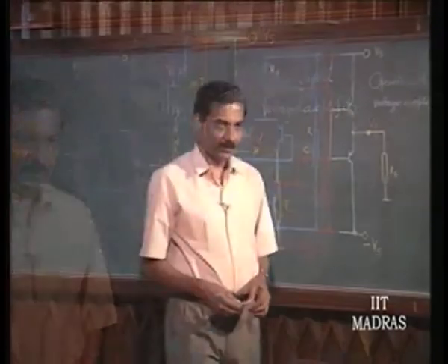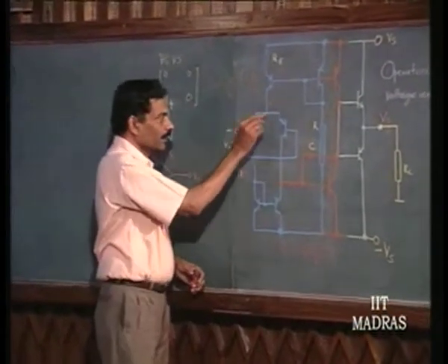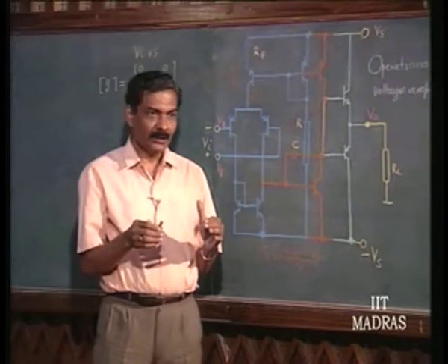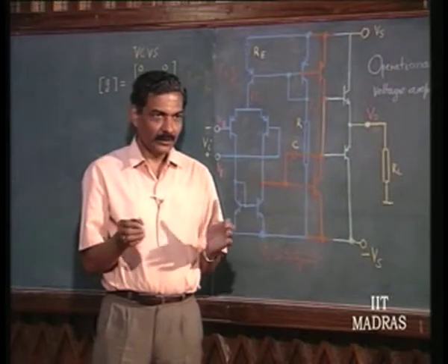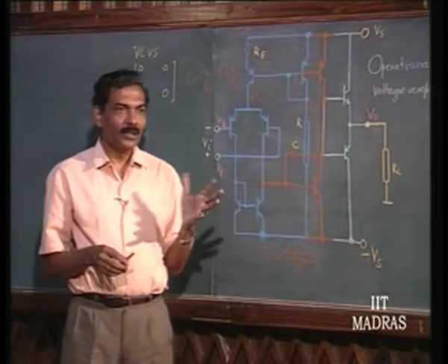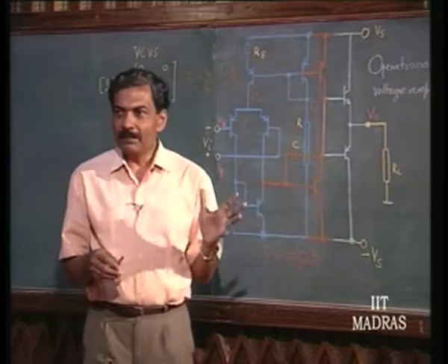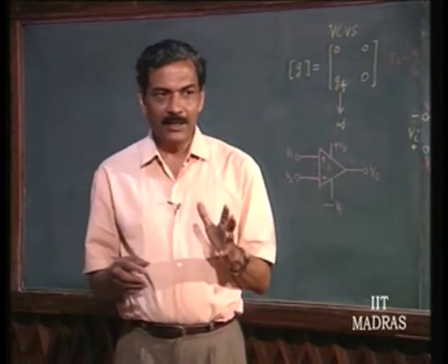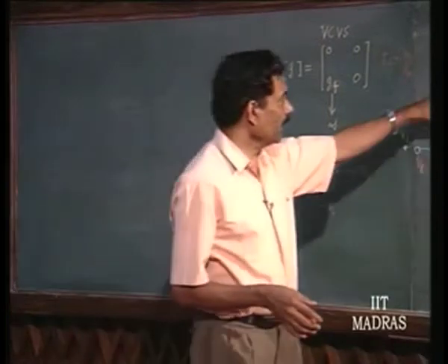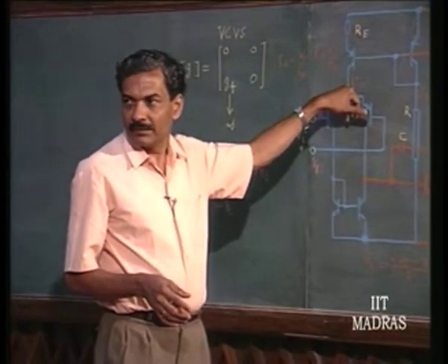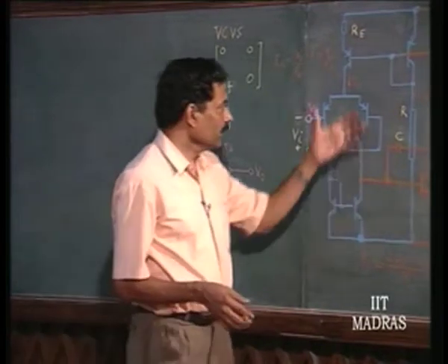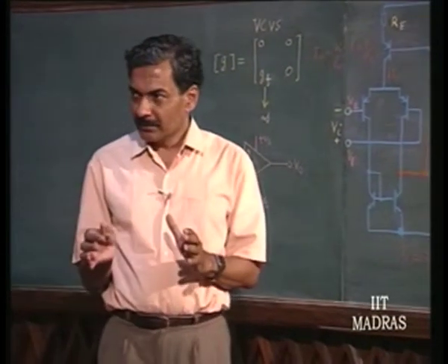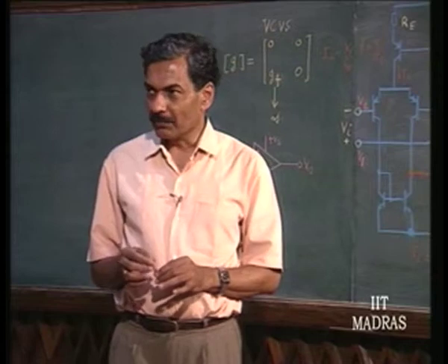few microamperes. And typically, therefore, the input resistance of this, which is going to be (beta plus 1) times 2 Re, is going to be of the order of mega ohm or so. Why? Mainly because you are operating at current of the order of microamperes, Re being equal to Vt by I2 by 2. So, you can evaluate the input impedance of this stage. It has been made on the open loop to be of the order of mega ohms typically.